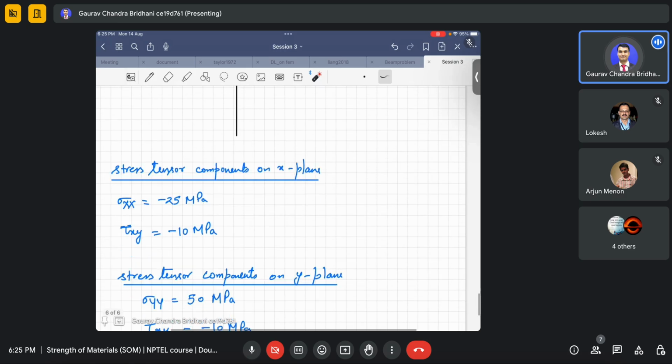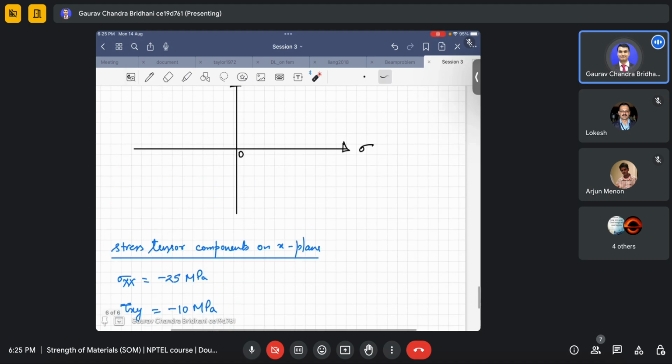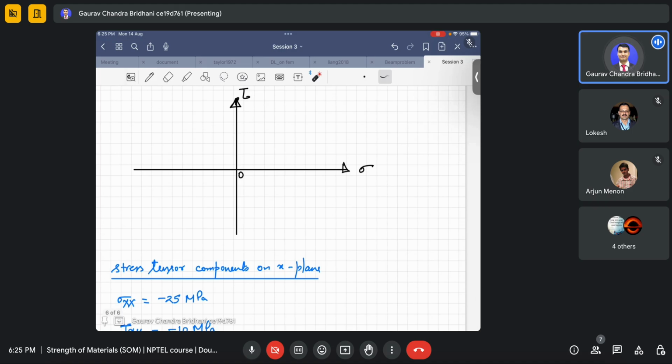But here in this question you have a negative shear, it's not positive. That means we have to do the reverse of it. So if the positive shear is plotted downwards, the negative shear should be plotted upwards. Okay, and that's why I chose this question, so that you should be aware, remember that property.